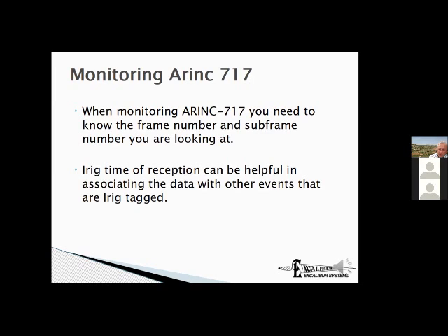So what we've done in our cards is that we take that mark, and from that mark, we start a microsecond counter from 0. And then we give you what ARINC gives you, which is the day of the year, and the hour and the minute and the second, and we add to it the microseconds into that second.